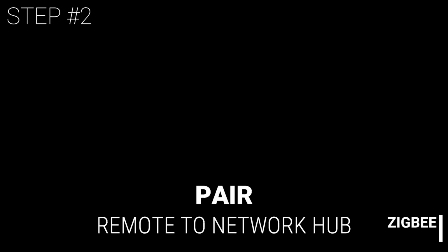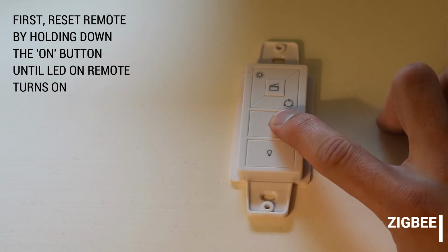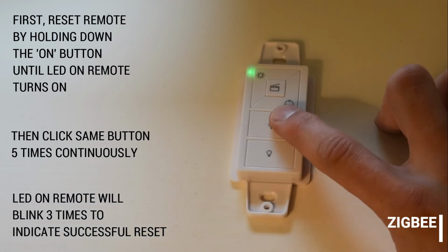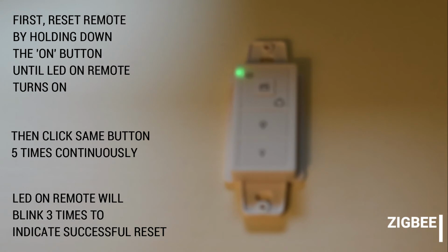The next step is to pair the remote to the network hub. In order to factory reset the Zigbee wall button remote, hold down the on button until the remote LED turns on. Then, click the same button 5 times continuously. The remote will then reset.